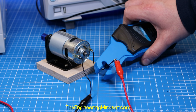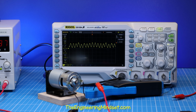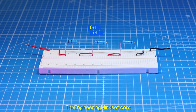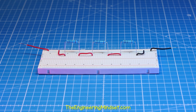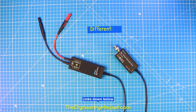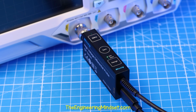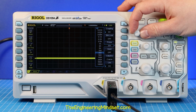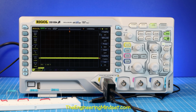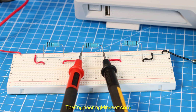We can also connect to things like this DC motor to see the current profile and understand the behavior, which could be very useful. If we have a known resistor in the circuit, we can use that to measure current. For mid-circuit, the easiest way is to use a differential probe set. Ensure an appropriate range is selected and that this matches the channel settings on the oscilloscope. Adjust the scale to suit the circuit if needed. Then probe across the component.